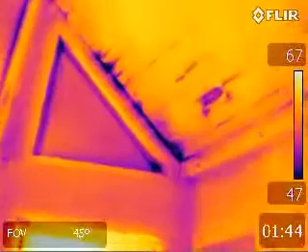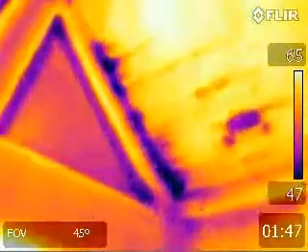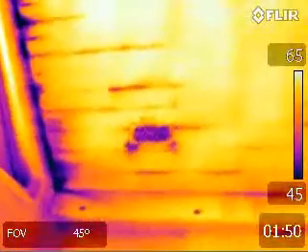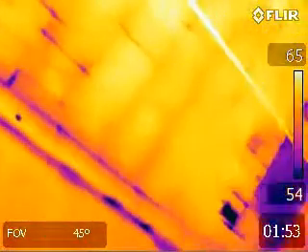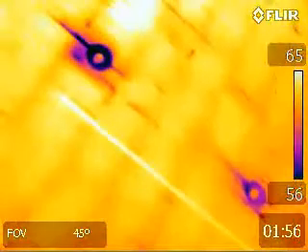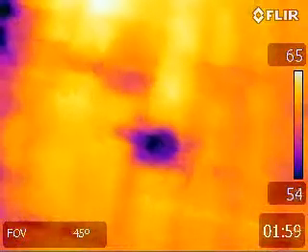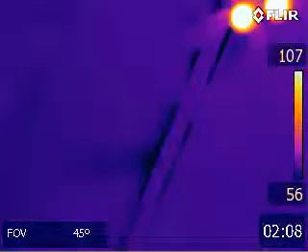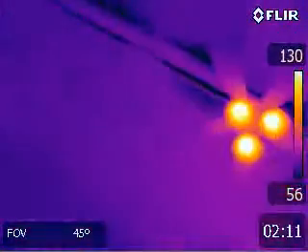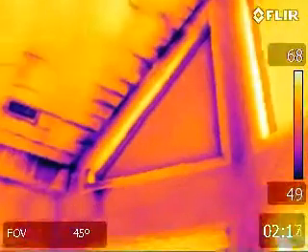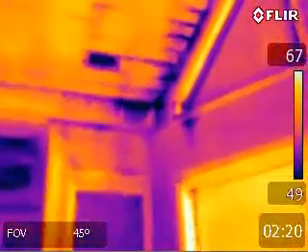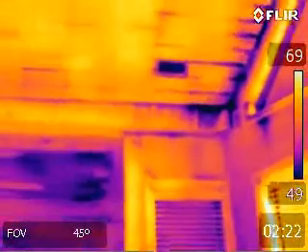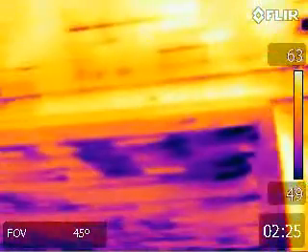We can see here in the corner some air infiltration. We also see air infiltration in the tongue and groove ceiling. Although the amount of air infiltration and exfiltration is not excessive, the problem is where the exfiltration is taking place in the ceiling, allowing even more warm air in the wintertime, of course, conditioned air to escape into the attic. The house is working like a chimney, so the air leakage is going right up and into the attic.